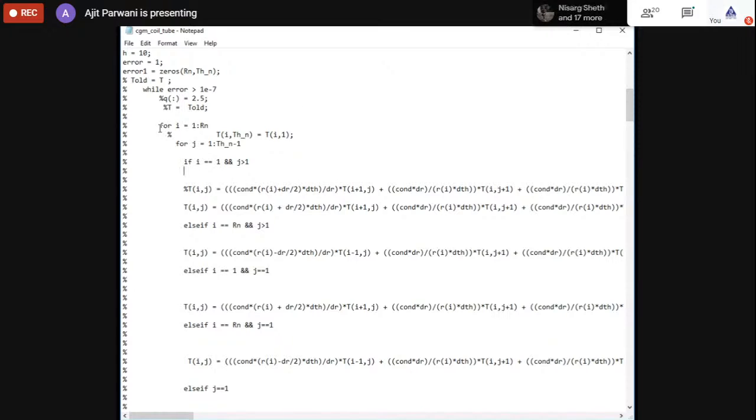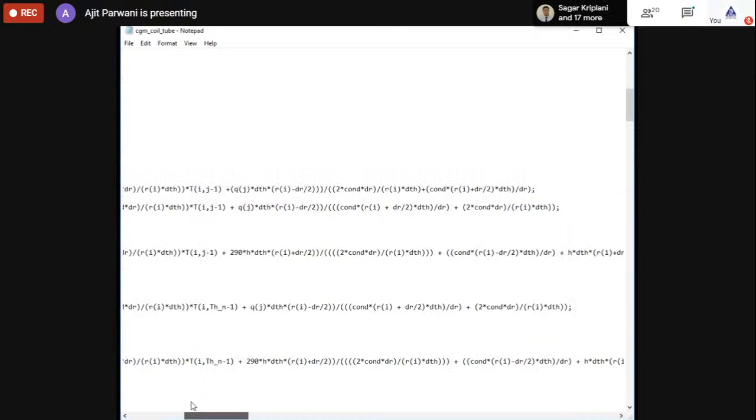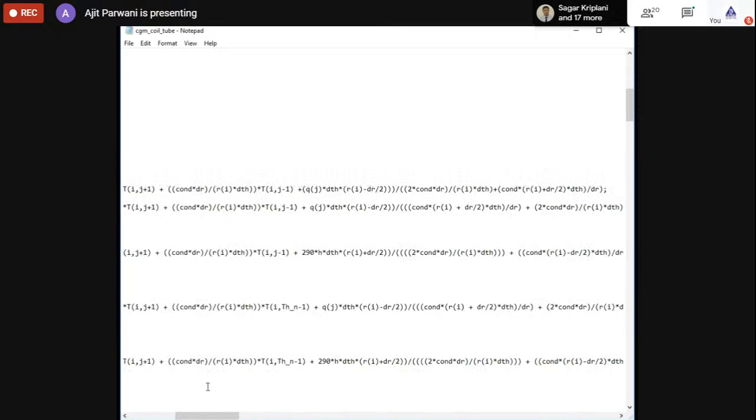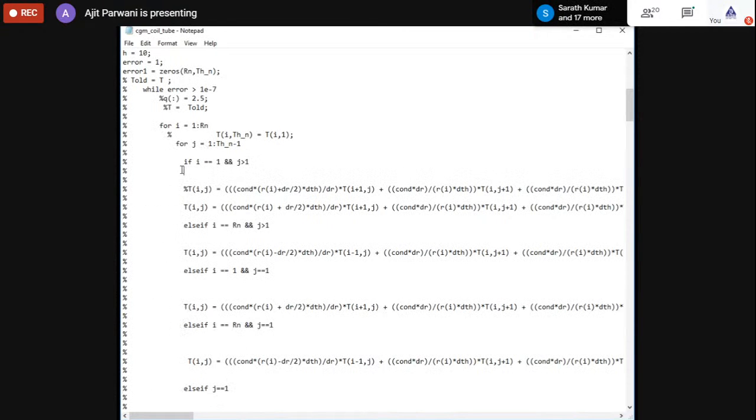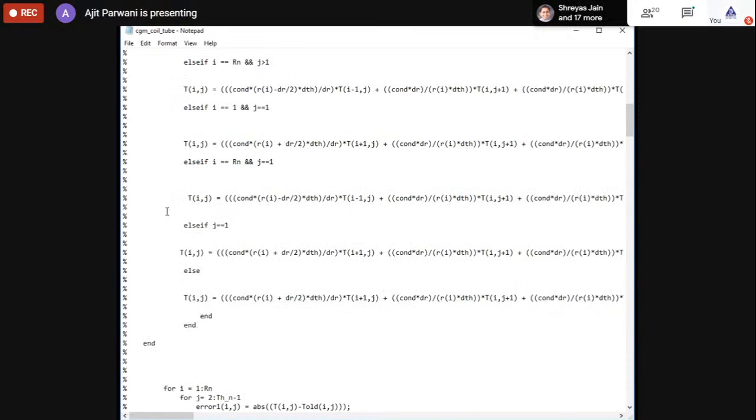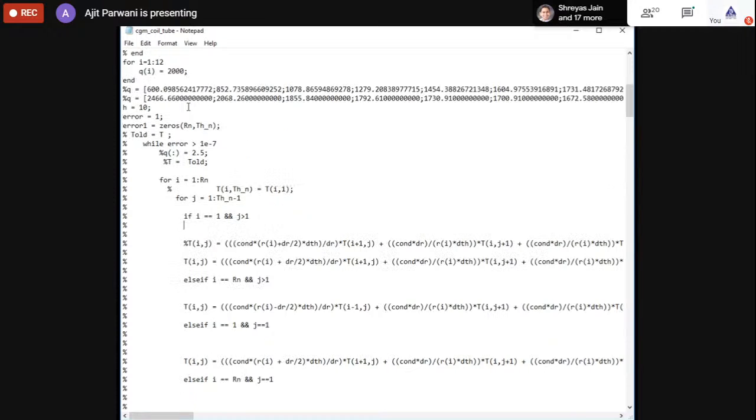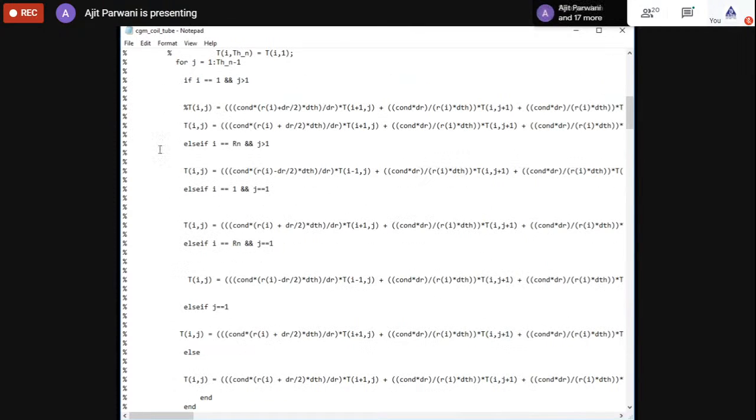So you can form the loop, and with that loop you will get the value of temperature, like APTP is equal to AT plus AWTW upon something. Depending upon the boundary conditions, you will form the loops, and when the loop is solved it will terminate, and finally you will get the temperature at all the 25 points.